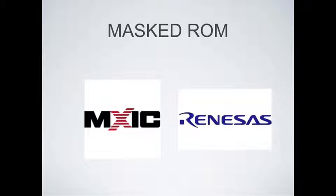And so what masked ROM is, is where the transistors are arranged in the chip before manufacturing. So they decide, they encode all the data that you want encoded into the memory space, and then they basically manufacture the chip like that. So you're not going to be able to change it after it gets to you.